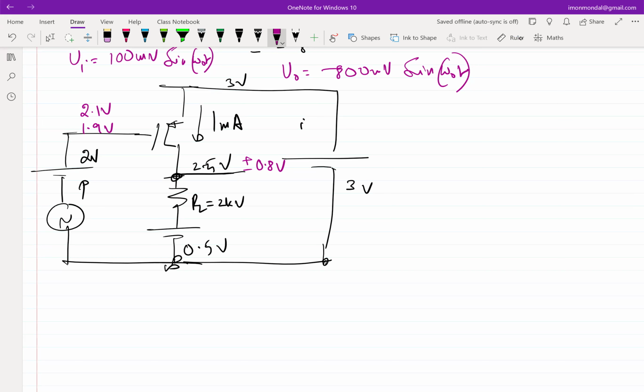I could decrease, right? So yes, basically, I agree. This voltage looks like we are working at the edge. So I back off from the edge, right? I reduce from 2.5. The quiescent need not be 2.5. It can be lower, and ideally, if I lower it by 800 millivolt, then I'm good, right? But given the circumstances that we have, what is the first thing that you would like to change?